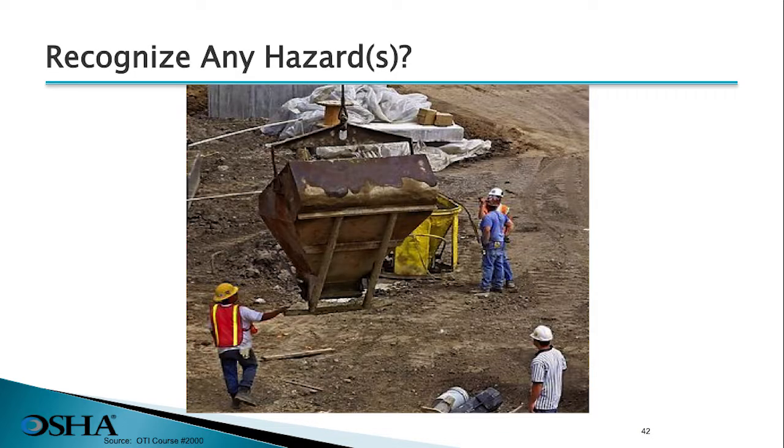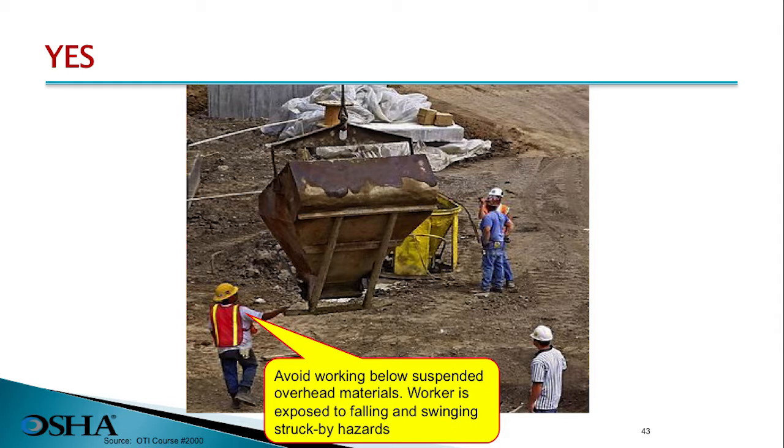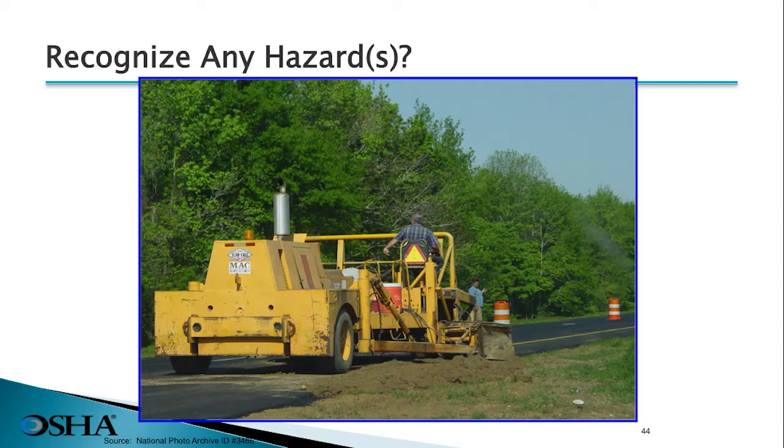On this job site, can you see any hazards? This worker is working below suspended overhead materials and is exposed to falling or swinging struck-by hazards. Can you recognize any hazards on this job site?